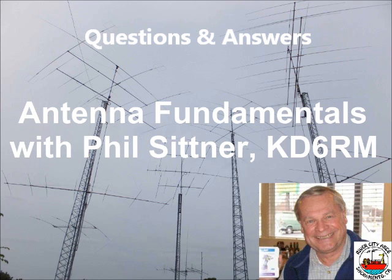But also because the feed line resonates. So basically, if you have an electrical half wave of coaxial line, the impedance you have on one side is exactly the same as on the other side. But if you have a shorter distance, or a quarter wave, then it's different. That is why, when you read the SWR, it's important to add a piece of coax and see if you have the same reading on the two SWR meters.